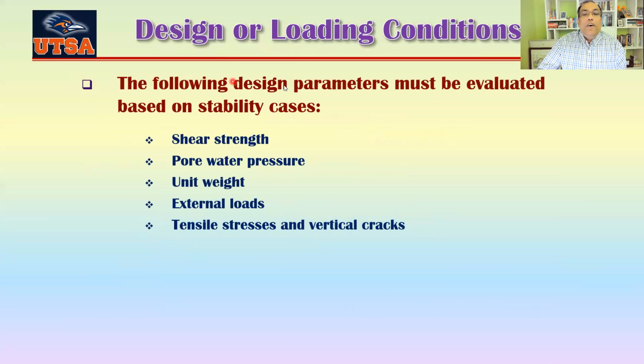These are the following parameters that you must consider based on the stability cases: the shear strength, pore water pressure, unit weight of soil, external loading working on the slope, and tensile stresses and vertical cracks, or the cracks that develop because of tensile stress, sometimes called tensile cracks. So, is there any tensile cracking or not?